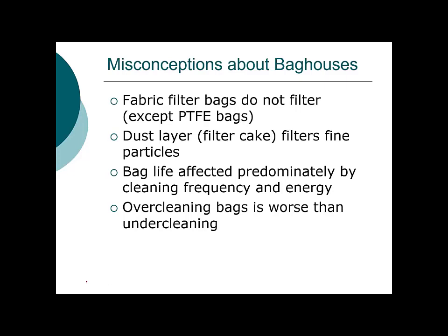So just some misconceptions. The fabric filter bags don't just filter. You went through the mechanisms by which they're actually removing. They're not sieving. And the filter cake does provide a significant improvement in the efficiency because it can filter finer particles than the fabric itself.